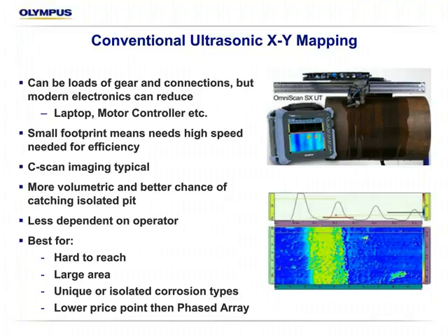So these are definitely best for hard-to-reach areas if you don't have access. Scanners have the ability to be steered and driven up to the top of a tank, that kind of thing. For larger areas, obviously we can't take a ton of thickness gauge readings in an efficient amount of time, so the go-to was conventional ultrasonics with a motorized scanner.